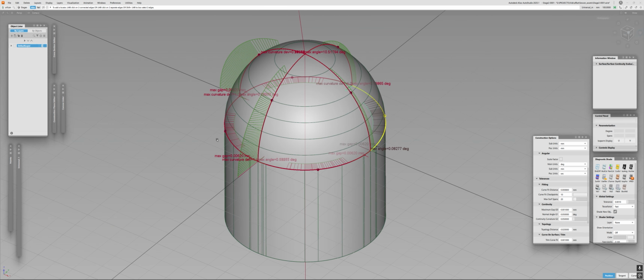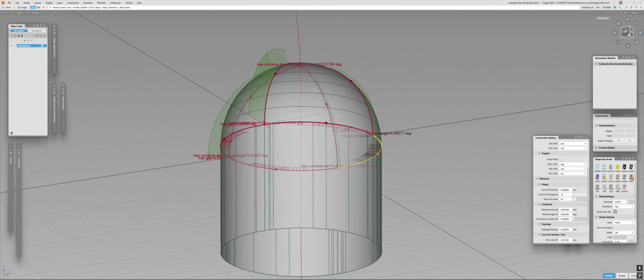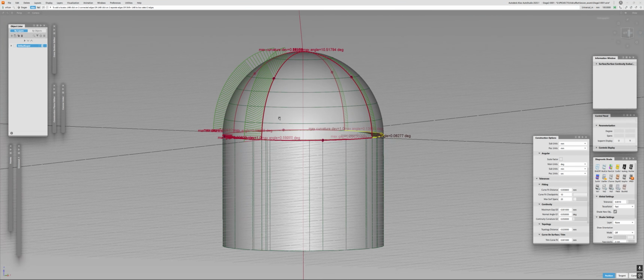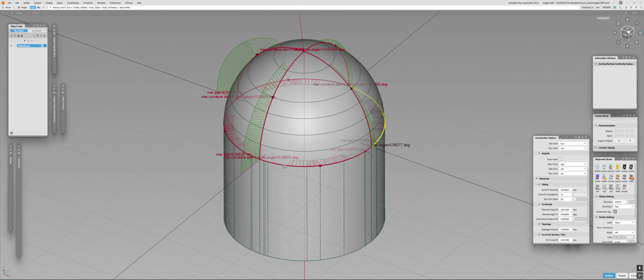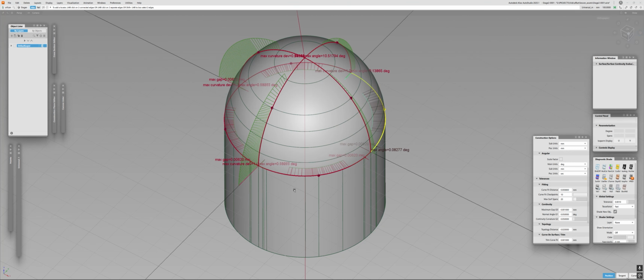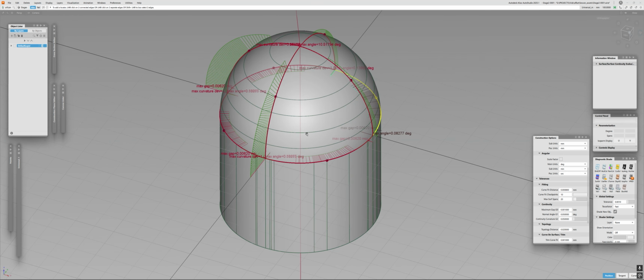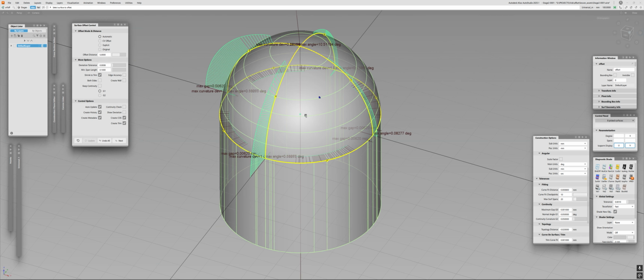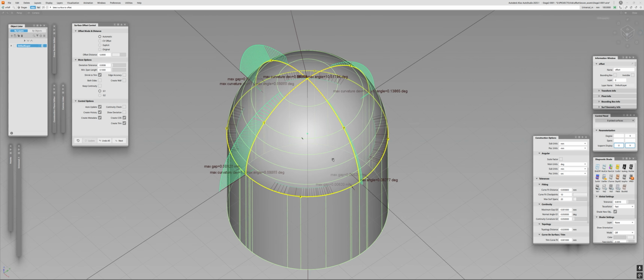Because it's really common, especially on the periodic things. Losing positional tolerance is quite often. And this is a big no-no, so we need to fix that. We can live with the problem with the tangency and curvature if it is an inner shell, which nobody will see. That's okay. But if you are lacking a position within the specific tolerance set, now mine is very tight, I already mentioned that, but for me, this one is bad. For some situations, it may be good enough, but one way or another, we have an issue.